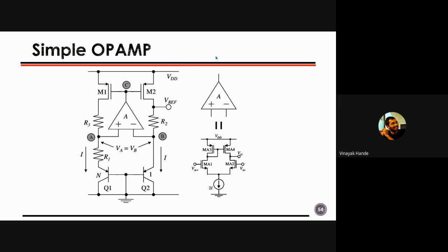Then, things to remember before proceeding ahead. I am having the simple op-amp. Generally, whatever op-amp you are using while designing a voltage reference, you don't have to go for a two-stage amplifier or three-stage amplifier or four-stage or something like that. It is not at all needed, because first of all, this circuit is kind of a DC circuit, so you don't have to bother much about the frequency variation. So you can realize the amplifier with a simple differential amplifier.